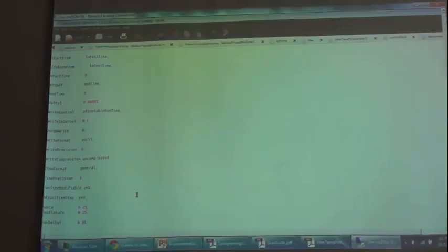Inside every run-time loop, there will be two header files, CourantNo.h and then setDeltaT.h. So you will keep on checking every time. You will read the Courant number and the current delta t, and then it will give a new delta t, if you choose this option.